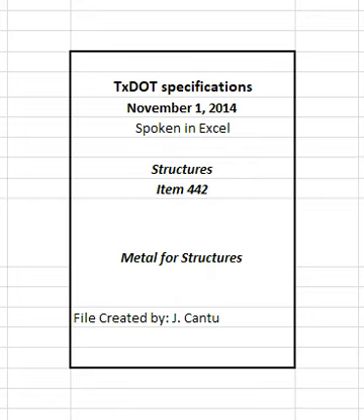2.7 Aluminum. Provide aluminum materials that meet the standards shown in Table 4 unless otherwise shown on the plans. Table 4. Aluminum Standards. See table in specifications. When testing is required, cut test specimens from castings from the lower 14 inches of the tension flange, but not at the junction of the rib or base. Flatten the curved surfaces before machining. Provide standard test specimens in conformance with ASTM E8.